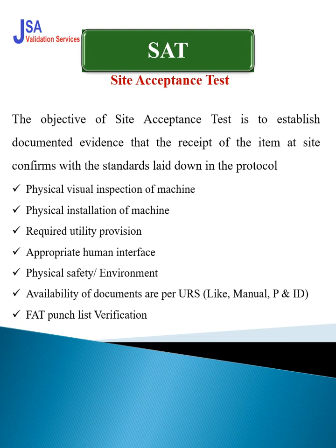Means the FAT that we have performed, if any recommendation or shortcoming is identified during the FAT, we have to make the MOM, that is called the FAT punch list. So before going to the installation qualification, whatever our recommendations are will be verified in the SAT. Okay, this can be clubbed with the installation qualification. So some companies perform SAT, and some companies include this test in the installation qualification.